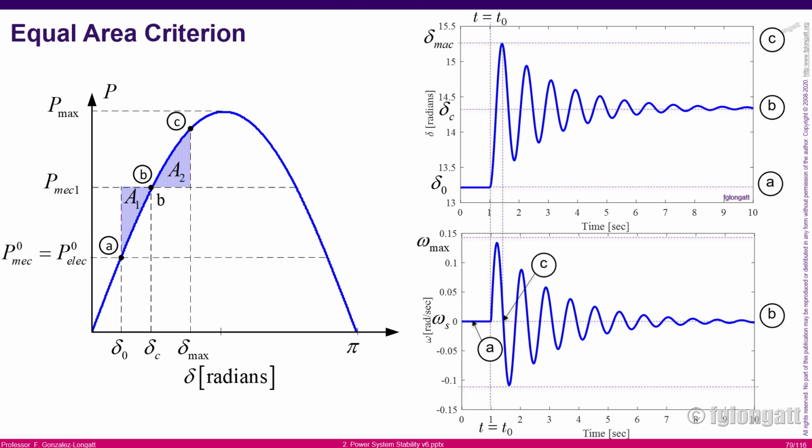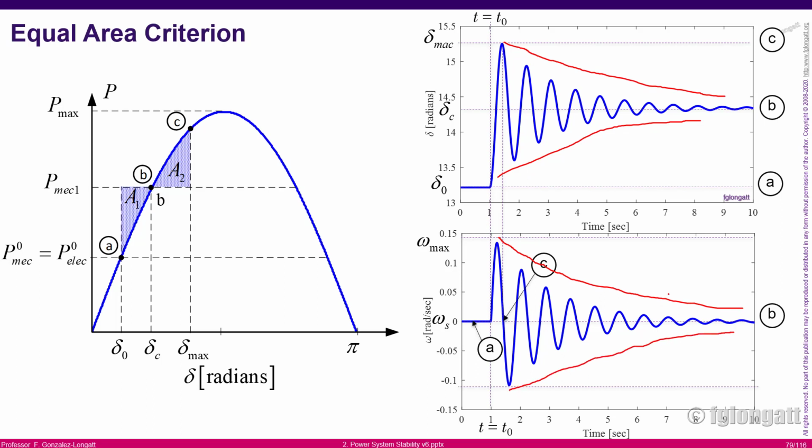We care so much about this kind of plot because we want to see this important damping characteristic over here, okay? If we see that, we will say the system is stable. Now, talking about the rotor speed, you can see the rotor speed is decreasing in amplitude and also reaching a steady state. That means this system is stable, okay?